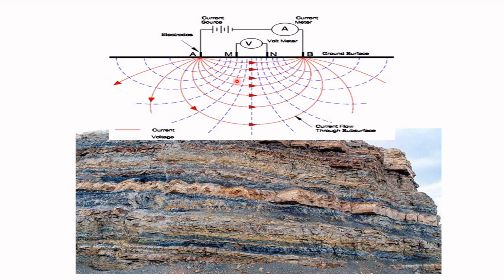Whenever the excitation reaches any longer distances, it will affect the measurement. That is why we are shifting the potential electrodes also in some resistivity methods. The influence of a particular piece of ground that is close to the source and the setup has a strong measurement, and the parts that are far will have a low measurement.